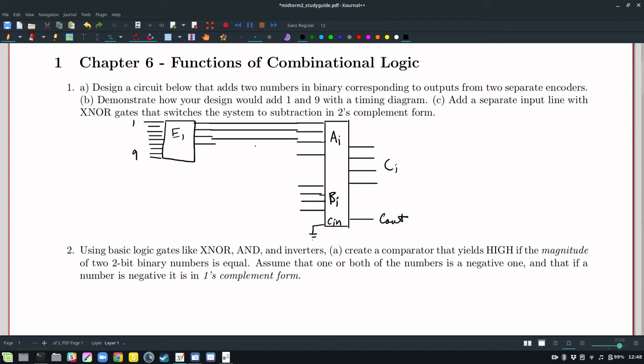Probably we're going to want to do active low. We'll connect this output as well, like that. And so let's make this active low by putting little inverter symbols here, 1, 2, 3, 4, and then we would want to do active low on this side as well. That way, when you actually press a key, it goes from consuming no energy to consuming energy temporarily and then back. So this is your supply voltage, and this would be ground. And so as soon as you ground something, then there's a current that flows, et cetera. That's a minor detail, and honestly, the logic could function active high or active low.